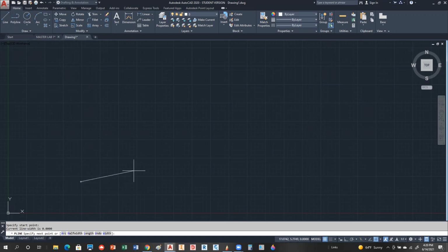They're basically the same thing because you might recall last week when we talked about this, the width of a polyline is always equidistant. So from the polyline or the line itself, you're going to be the same distance left and right of that line. So I usually just use width. I'm going to go down here and give it a width value. It wants to know a starting width and an ending width because we can taper this thing. So you could have a width of like 1 unit taper down to 0, so it would make like an arrow kind of look to it.